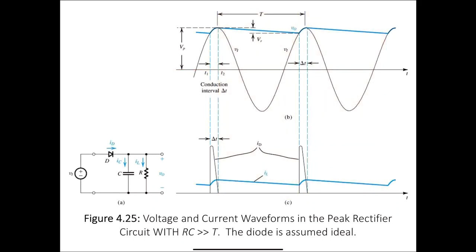During the charging interval, the voltage is applied across the resistor and the capacitor, which causes it to charge. Up here we have the voltage, down here we have the current. And so you see that there's a very significant current spike during the charging interval that corresponds with the energy transfer that's required to charge.